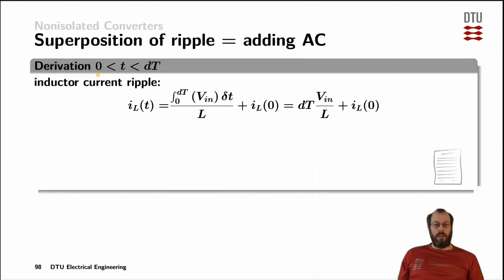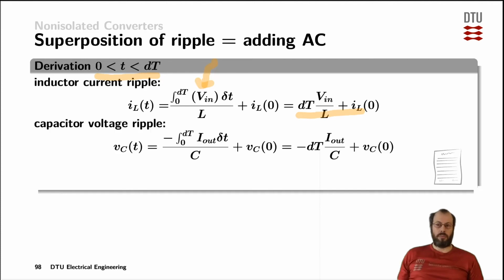Now, if we again relax the requirements we made when applying the averaging approach, here during the on time of the transistor, we can again put the equations that we derived from Kirchhoff's voltage law across the inductor inside Ohm's law, and we see that the inductor current is actually a function of time, a first order function of time with an offset. And using Kirchhoff's current law for the inductor current, we have the negative output current flowing through the capacitor during the on state of the transistor.